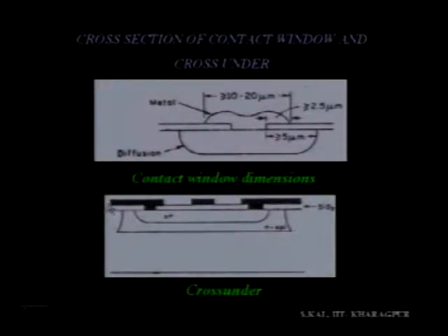Now we open a contact window here and here, then this metal line will end up here, and here again this metal line will contact in this contact window, so that here you can get a conducting line from this, then it is coming here through N plus, and here again it is a metal, and then again the current is flowing in this direction. Then from this point to this point you will get a clear gap, and this gap is what? The top is the oxide layer, silicon dioxide, and over this silicon dioxide another line can cross easily. This is known as cross under or underpass.